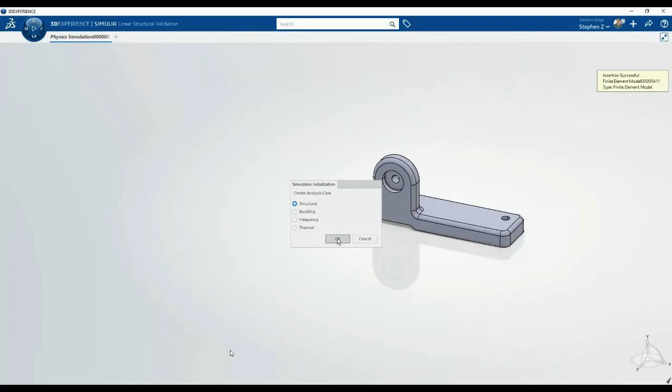We can certainly open it and mess around with it as long as we don't save it, and we can close without saving, and then that data integrity remains intact. But if we're dealing with structural mechanics engineer, and then we go ahead and save that data, then the structural designer is no longer going to be able to open it. So it is a one-way street. I just want to make you guys aware of that because it does rewrite that data in the background, which is why in this demo, we're just going with structural designer. We don't need any exotic materials. We don't need any contacts or anything like that because this is just a bracket part. But the base level, it is a one-way street. As soon as we save it in the higher level, the base level is no longer going to be able to open it.